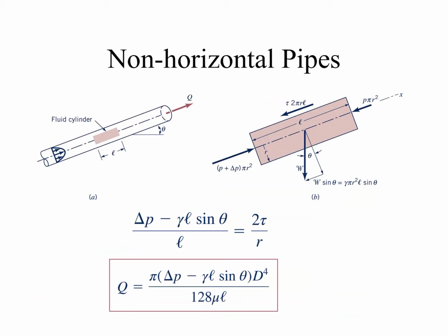The other quick comment that I'll make for laminar flows is you could do the same derivation and include the effects of gravity. Remember, thus far we've been dealing with a horizontal pipe, and if we don't deal with the horizontal pipe, then we have to add this term to our derivation. And what that ends up doing is modifying our shear stress. Remember before, for a horizontal pipe, this was not part of the force balance.